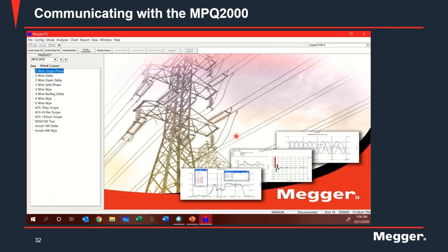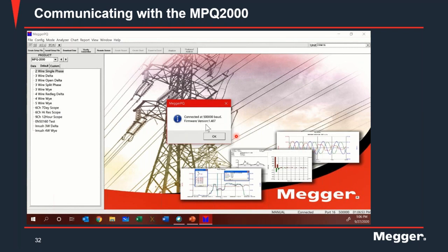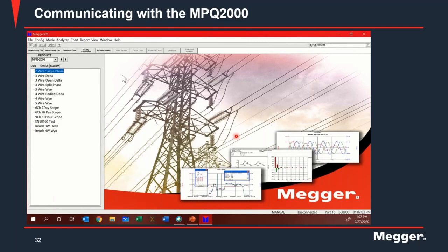Communicating with the recorder: you can establish communication between the unit and the laptop, and the way of doing that on the software is either by an Ethernet cable or through a USB cable. Here I use the USB cable, and if you look at the top right, you will see a box which says COM16. When I connected the recorder to my laptop, it automatically detected the port number that was assigned to it, and then I can verify whether it's communicating with the unit by clicking on Verify Connection.